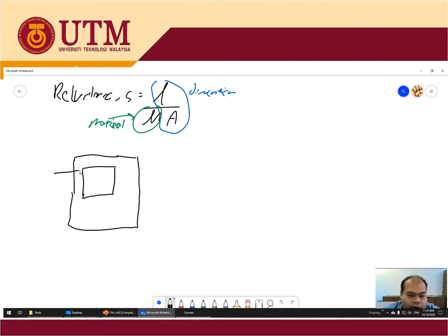The winding is maybe here. If you can see, the flux can flow like here. This means that this circuit is in series, because the flux doesn't split to any other part. The flux only goes in one path. So this is a series.